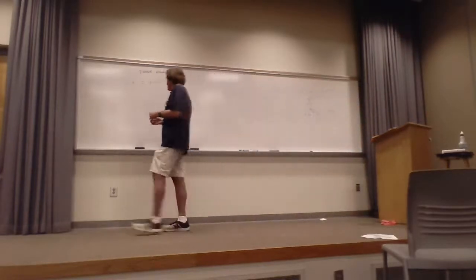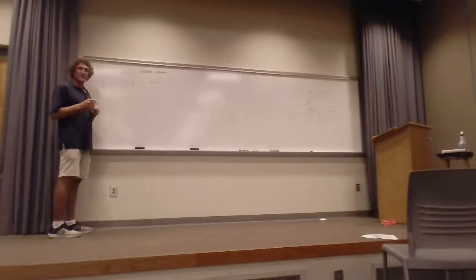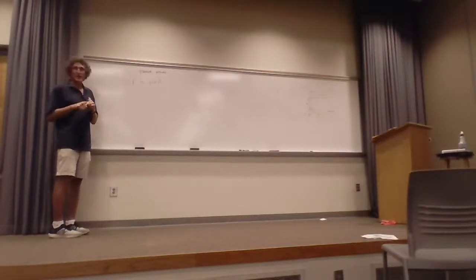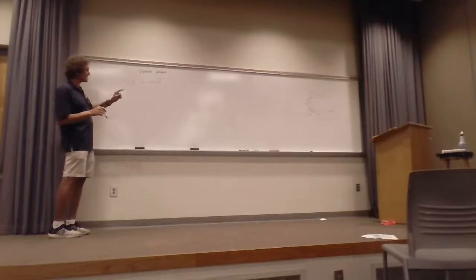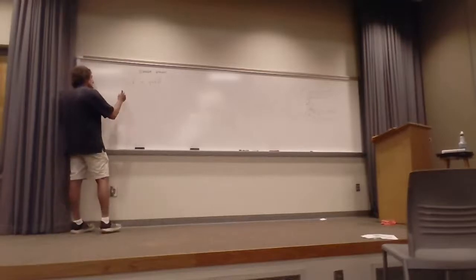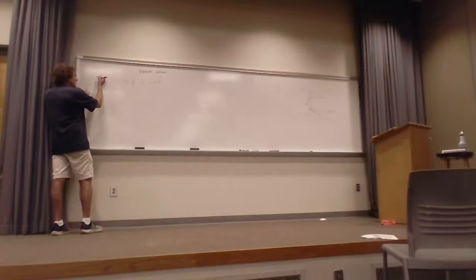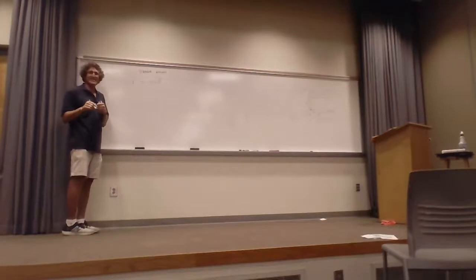Anyway, equations that directly apply start off with curl of E is equal to minus j omega mu H. That's Michael Faraday's law of induction. I didn't put it in the time domain form, and I already replaced B with mu H. We've done that for plane waves, if you remember. Next, we're also going to assume that in the center of the guide where the thing's bouncing, sigma is 0. You just write that down. It doesn't have any loss.